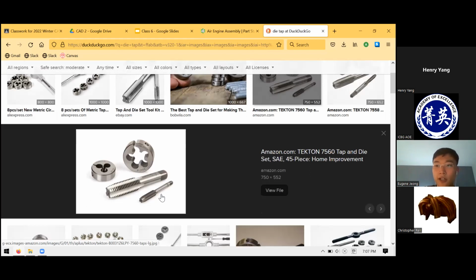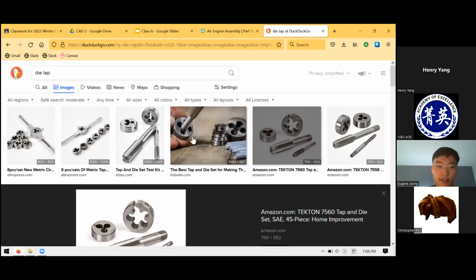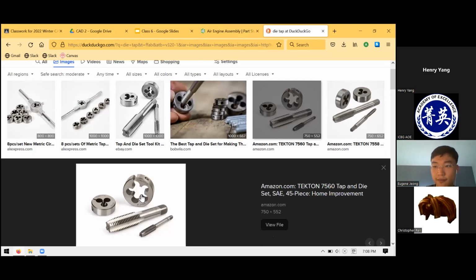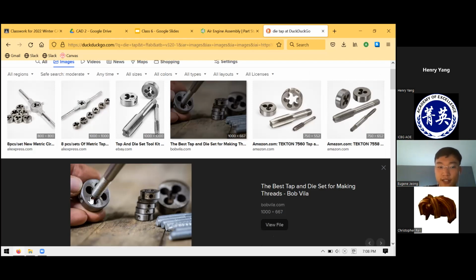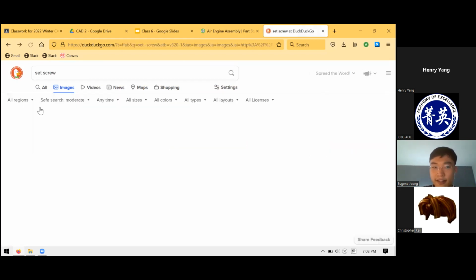And if you have a rod, you use a die to cut the threads out from the rod. In this picture, the person is starting out with a rod and then they twist it into the die. The die is basically the same thing as a tap, just the complement. You can see it has these cutting edges inside. As you twist it, it cuts these threads into your rod. I don't know if that's how they make screws in real life. I imagine it's something like that.